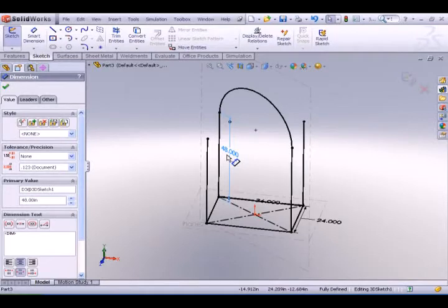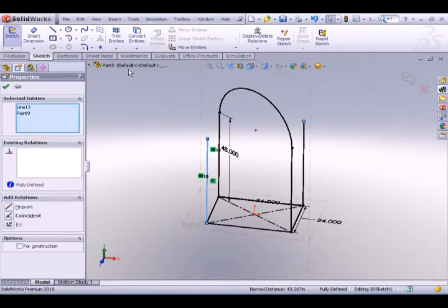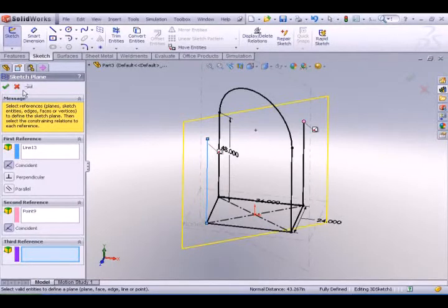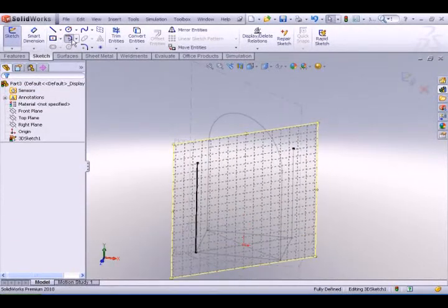Double-clicking away from a two-dimensional sketch will get you out of that two-dimensional sketch back in the three-dimensional sketch. But double-clicking in your three-dimensional sketch will actually exit it. It's kind of a nice shortcut, but it's also a little annoying. So I've got one more 3D sketch plane to make. Notice pre-selecting makes very easy work of that.